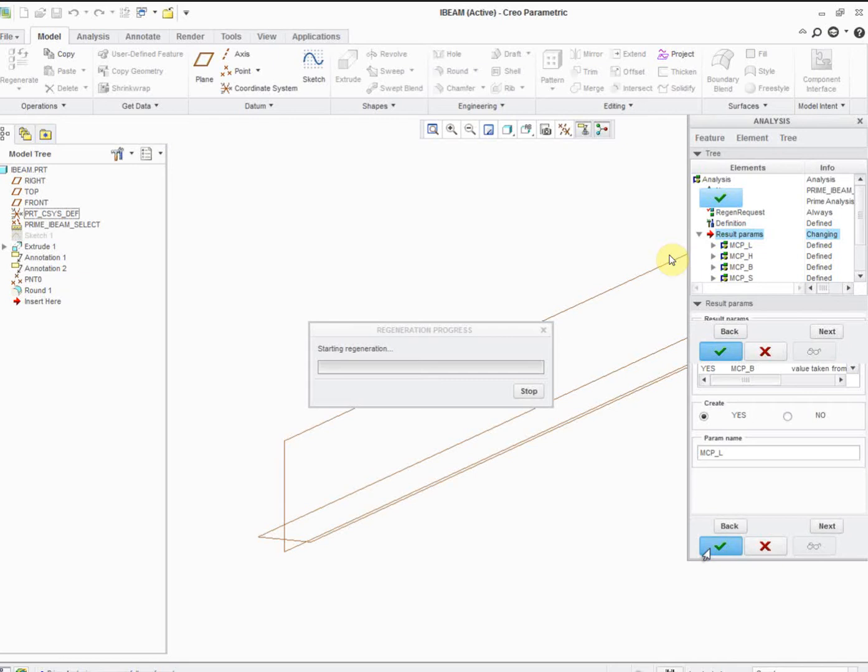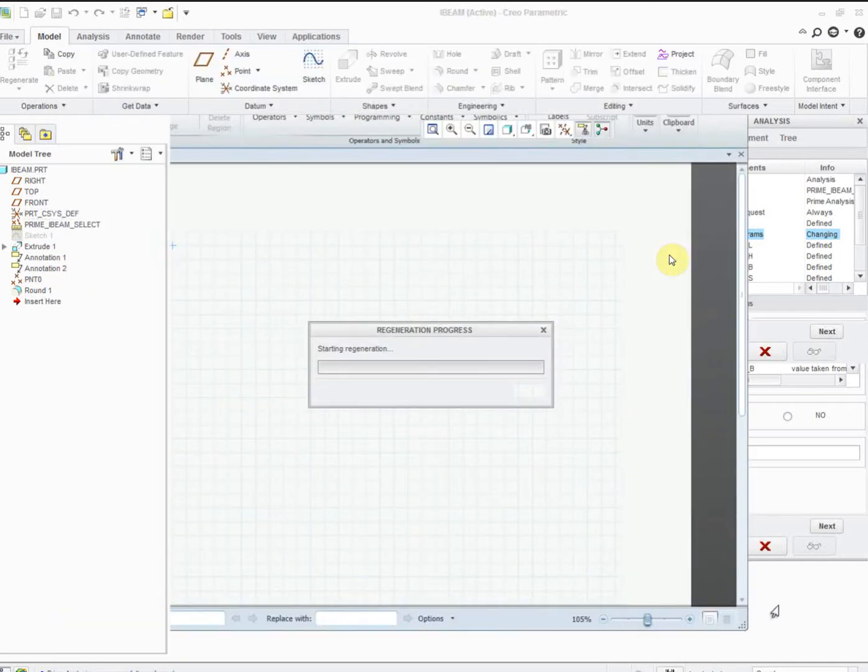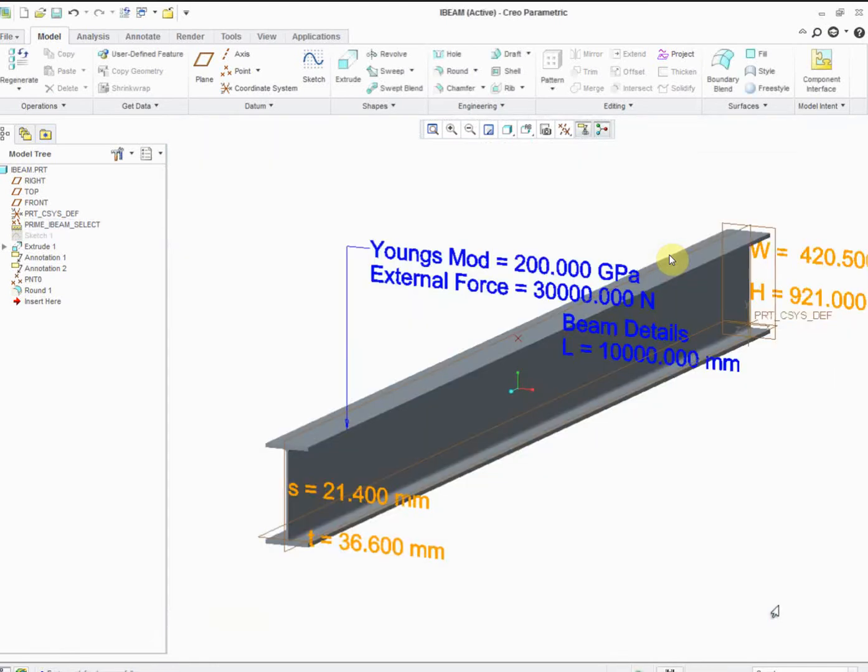Even though we saw the numbers change, as it looks in the 3D model, it's pretty much the same thing. But the whole point here is that now we can have one Mathcad worksheet. We can change one value. It's going to pull all the different dimensions that pertain to that particular part number. I don't need to do this one by one within Creo anymore, right? I can just do it within Mathcad, and then all those values will be ported over into Creo.